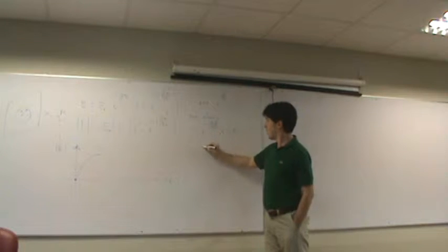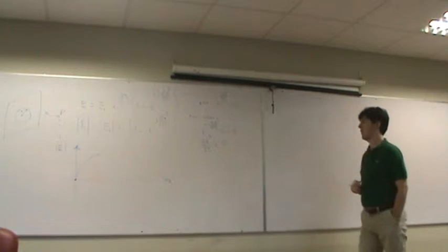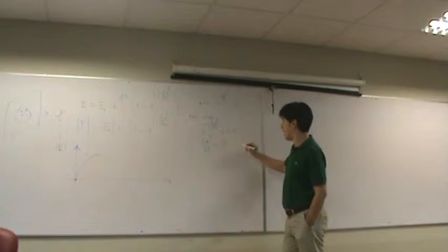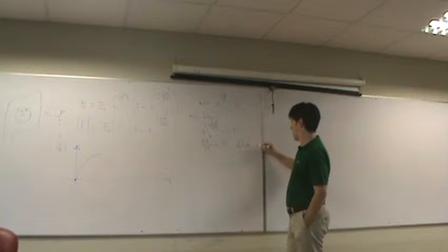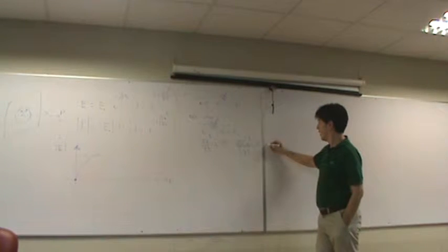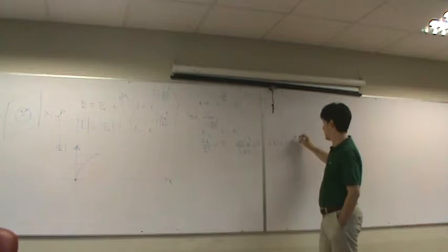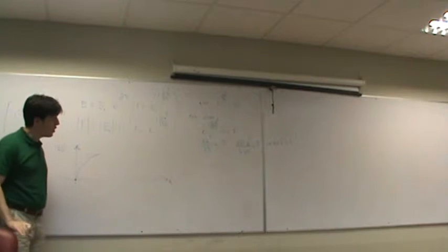This means that this happens when this argument is equal to B. And if we remember that beta is 2B divided by lambda, you find that the maximum is found when the aperture is square root of the wavelength times the distance.